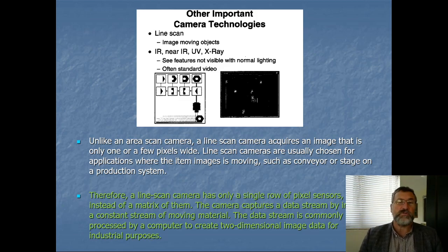You get something called barrel distortion due to the way the lens works. With this line, because you're just looking at a line, you get less distortion. It's more standardization. So the way it works is you have what they call an encoder on the conveyor belt, which measures the exact position of the conveyor. And then when it's in one position, you grab an image of the line. And then the conveyor moves a little bit, the encoder detects that, and you grab another image.